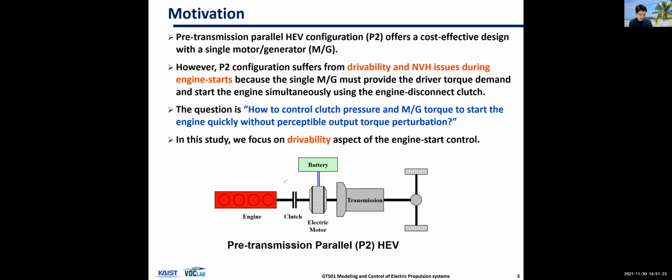And in addition, when you apply pressure to the clutch, unless you apply it in a very controlled manner, applying pressure on the clutch will also lead to reaction torque, right? Because if you start the engine and apply clutch pressure, that's going to create disturbance to the driveline, right?